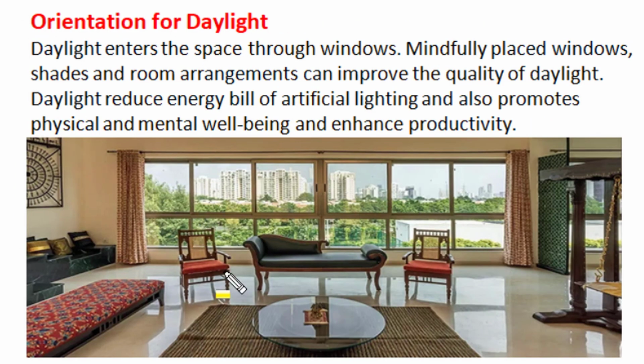Well designed fenestration ensures thermal comfort for indoor positions, but apart from temperature conditioning, fenestration also ensures natural uniform daylight. Daylight enters internal spaces through windows or glass panels or fenestration, and well designed fenestration with appropriate shade and good orientation of room can improve quality of daylight in indoor space.